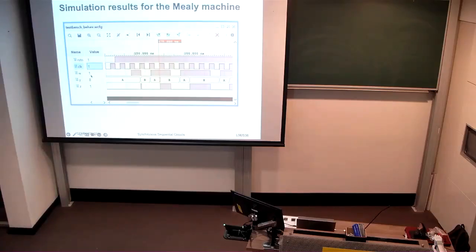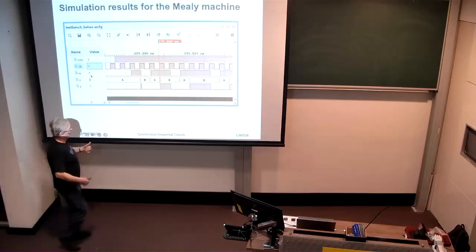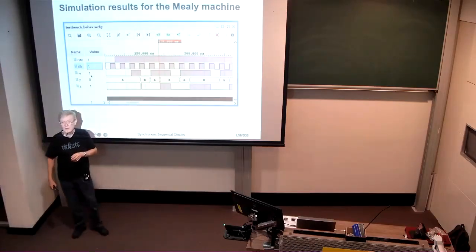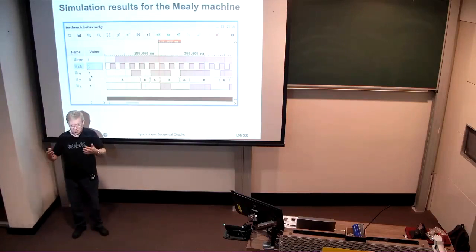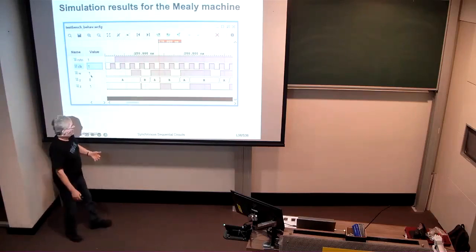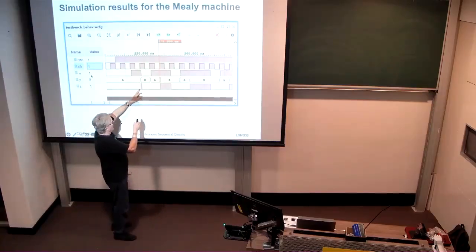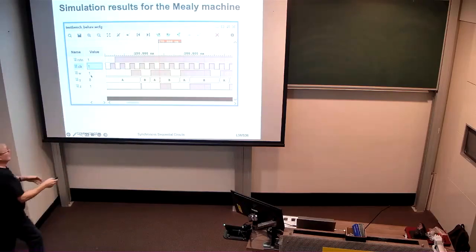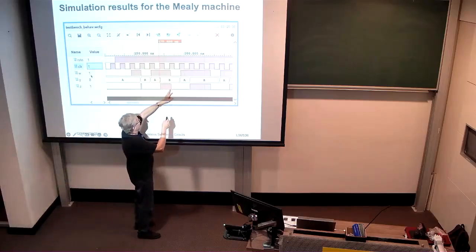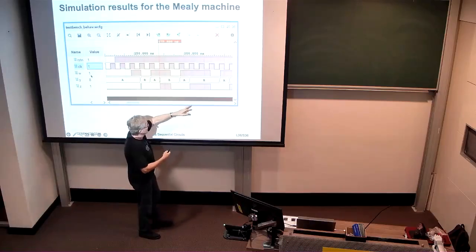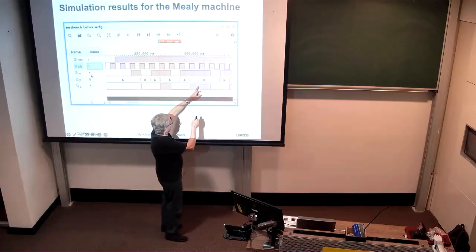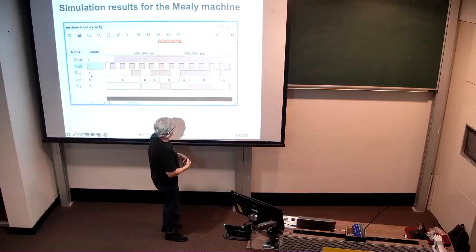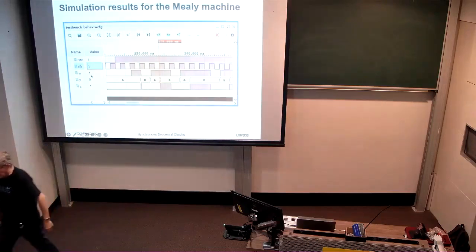And for that to be even seen by that circuit, it sort of has to coincide with a rising clock edge. Now, if the clock edges are coinciding, if they're happening at the same time, the downstream circuit isn't going to see a rising clock edge until here, and by then Z is long gone low, so it doesn't really matter, right? Whereas over here, we get a rising clock edge, Z's 1, so any downstream user will see that Z. Same here, rising clock edge, Z's 1. Same here, rising clock edge, Z's 1. So it's for 2 periods there, which is what we expected. So that all looks fine.